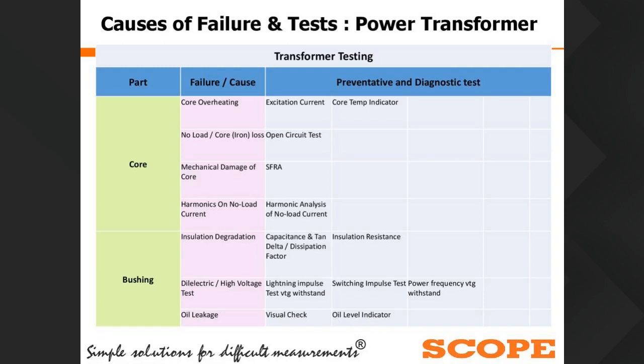Similarly, bushing. There are different types of tests, that is capacitance, tan delta, insulation resistance, lightning impulse, switching impulse, power frequency voltage, like that.